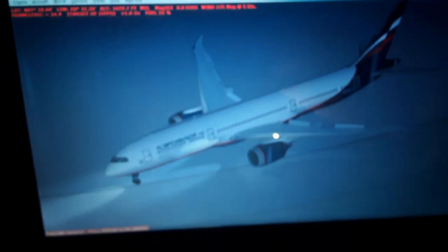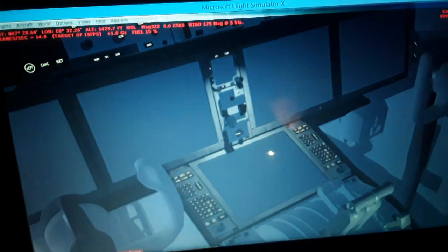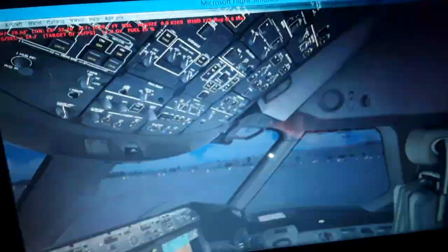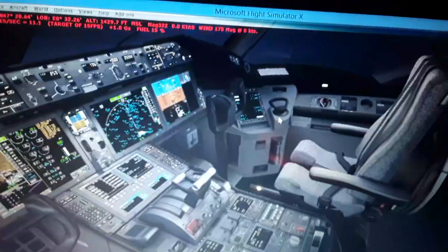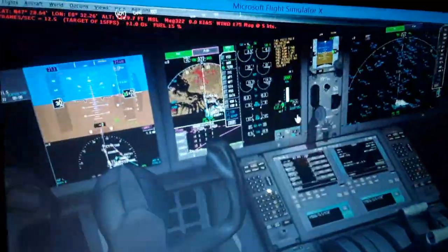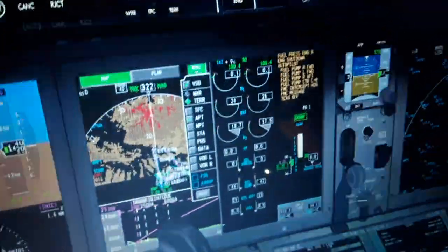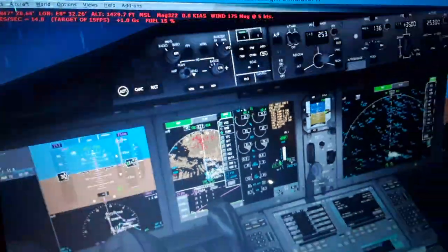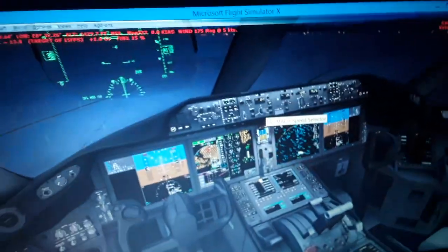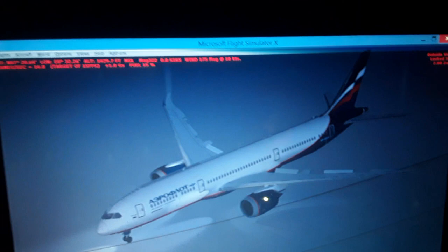So we have both engines off, we need to restart them. So we go over here in the overhead panel, very quickly set both auto start to the on position. Like this, you will see the amber indication, engine control, auto start. So we start the engines. You see pressurization is admitted from the APU right now, 20%, 20.3, 20.7, above 20%. We have pressurization here into the engines.